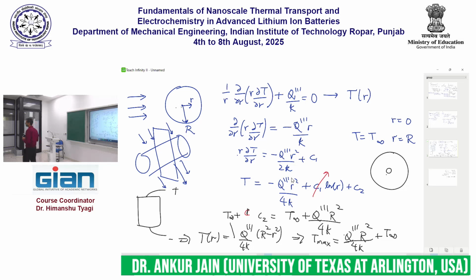For the same capacity of cell, if we provide the channel like that, then the size of the cell also will increase. Absolutely. You see, this hole is displacing material that could have stored energy. So the energy storage density of the cell will go down. I am sacrificing material inside the cell that could have stored more charge.